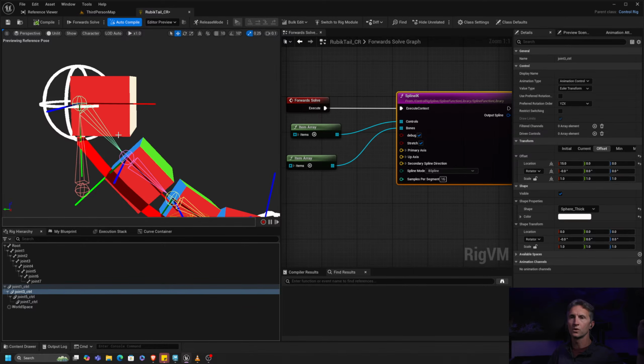So this tells us one of two things. We either need to build our own IK spline solver solution that works differently, or now that we understand how this works, we could add another joint to the base, and that base joint doesn't get affected. It's not the joint that we're bound to, so we would have a joint 0 effectively, and we would start at joint 0, and then joint 1 would be the first one that is actually getting the deformations. Seems a little hacky to me, but at least worth pointing out.